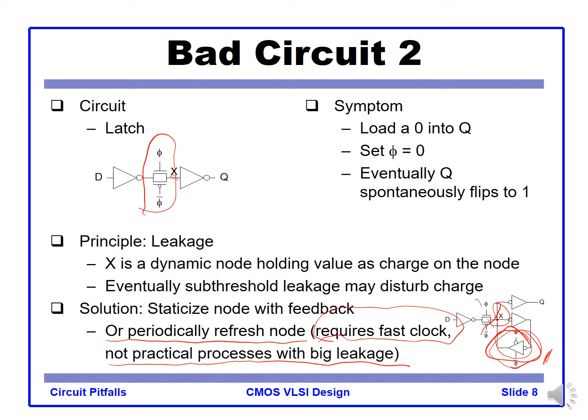In the special case that you really want fast logic and you have to make it work to satisfy your final goal, then you can try the dynamic logic by knowing the limitation. In that case, the test itself should be done with a very fast clock. So all the design issues and problems you have to know beforehand, right?